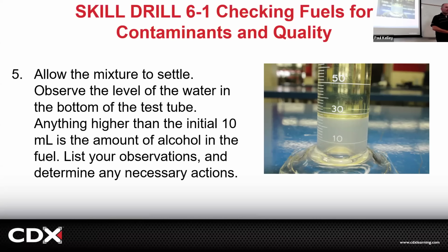Yeah, exactly. Now the water grabs the ethanol and now it's an ethanol-water mix. They just go together. It's hygroscopic. It's going to mix up and you'll be like, oh, wow, there's actually 30. But remember, we added 10. So it was really only from 10 to 30. It was about 20. And this one, in this case, a little bit less. So this may be like E18 fuel or something. And E10 is, if you roll up to the pump right now, you're pumping E10. It's 10% ethanol, 90% gas. This one was not 10%. This one was a little bit more.